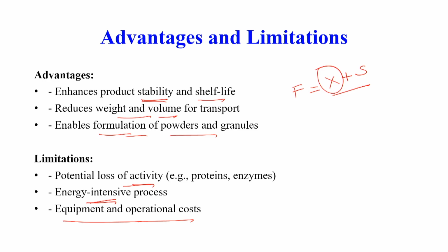So, today we discussed drying. Particularly, drying means you are removing the moisture content or humidity; you want to maintain a certain degree of humidity. How do we define the humidity? It is a relative term: the mass of water divided by the mass of dried material, that can also be represented in terms of the partial pressure of water divided by the saturation pressure, and that term is known as the relative humidity.